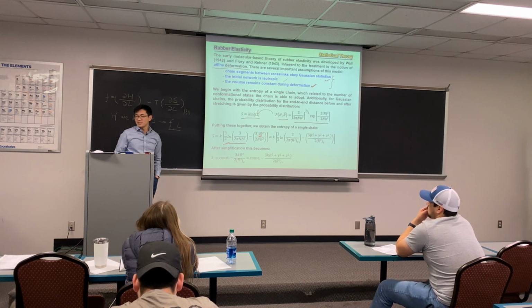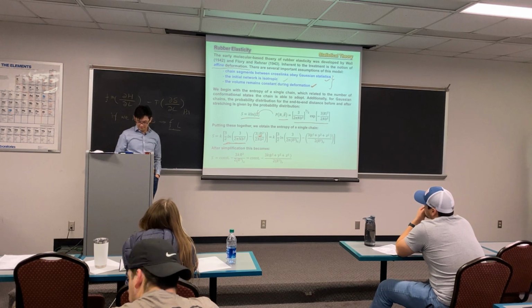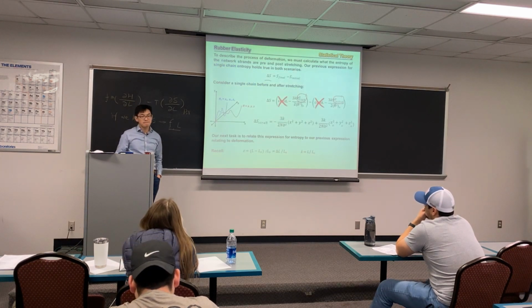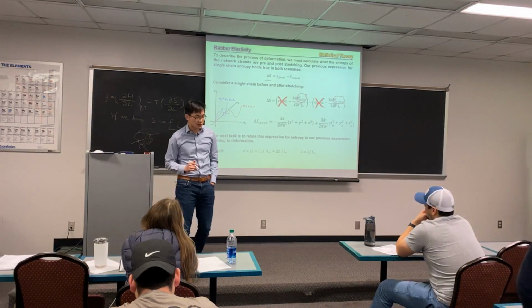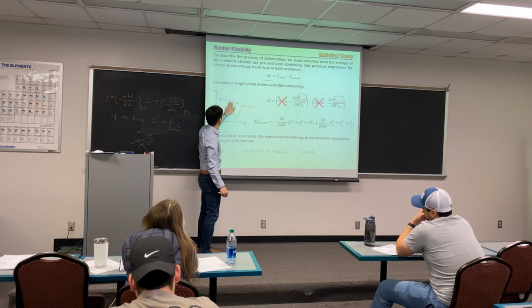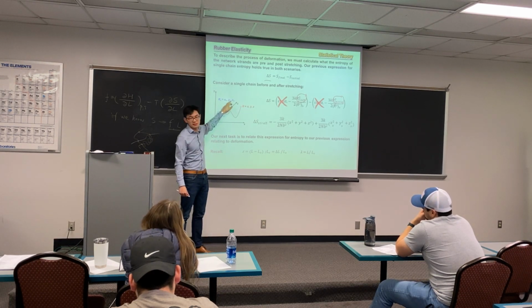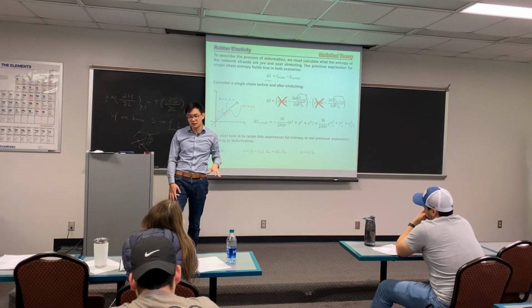Yes, right? Because if you know the deformation in one direction, and assume there's no volume change, what would be the changes in the other direction? Sorry, that's not going to be equivalent. Because if y also expanded to be twice of y0, and z is twice of z0, then your volume is not a constant, right?